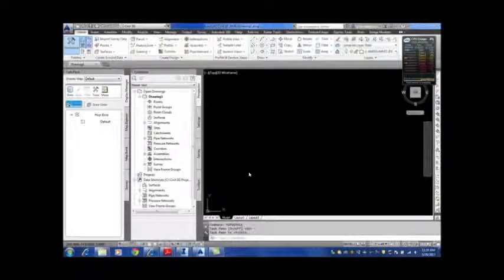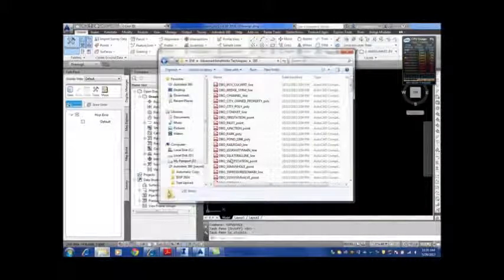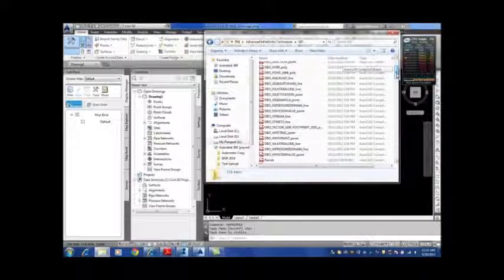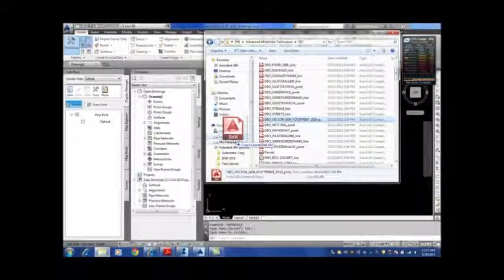If we were going to do a preliminary layout or just look at something preliminarily, we would probably go out and get some GIS data from either a municipality or a website or someplace that's got the data. So I'm just going to drop in some buildings and some parcels and then connect to a raster file so that you can see what you would be looking at if you were to bring this map data or GIS data into map. So I'm just going to bring up the GIS data and let's bring the building footprints in.